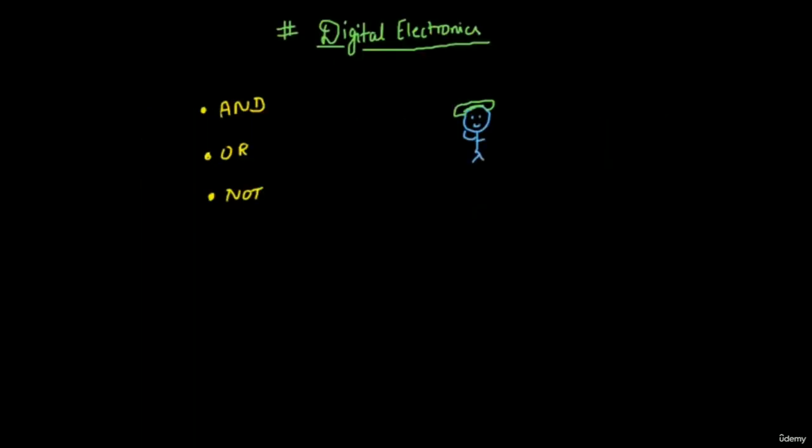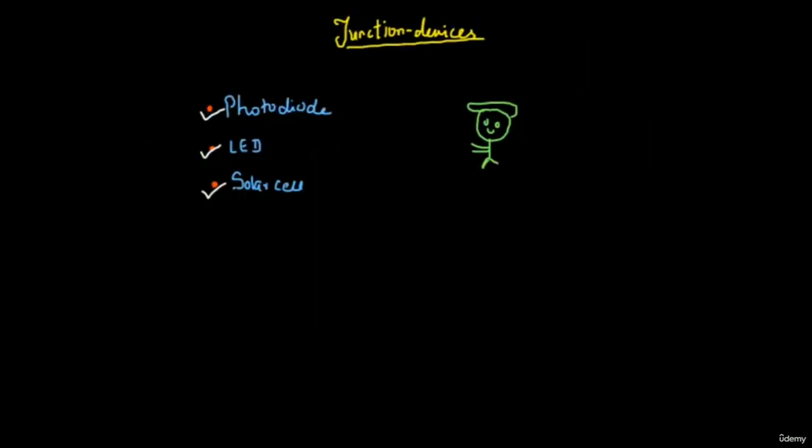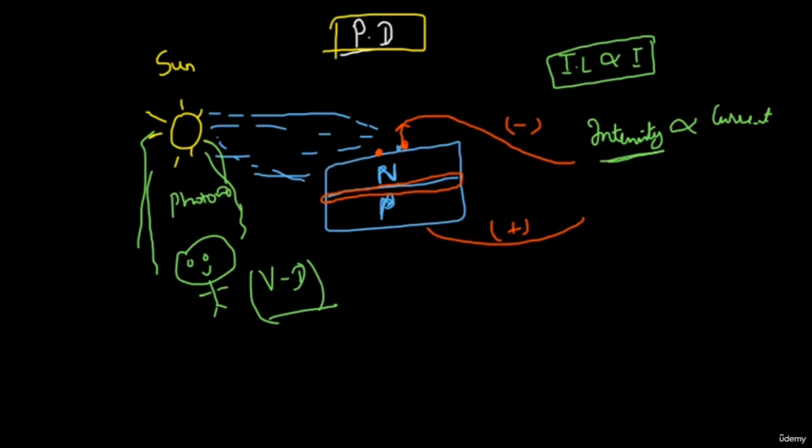So this is all about the photodiode that we have learned here. Photodiode means, now the name is making sense, I hope. Photons are falling on the surface and that surface excites the electron. When the electron gets excited and we make a system so that it can travel in the wire, we get the current. That simply means we get the voltage there, and we can use that to measure the intensity of the light. We can use it and make our devices work.